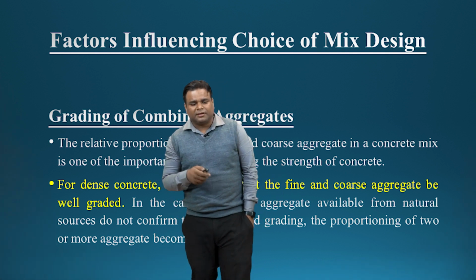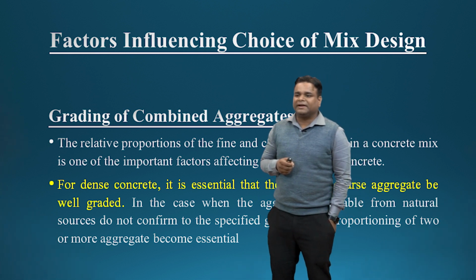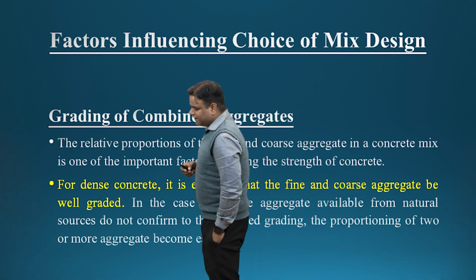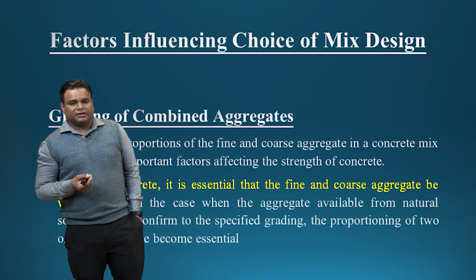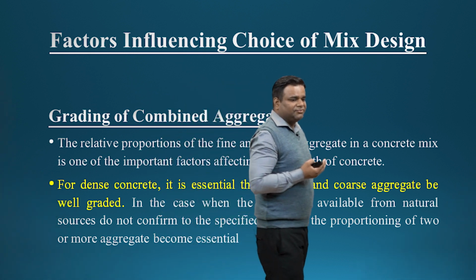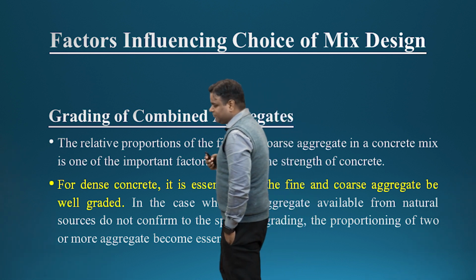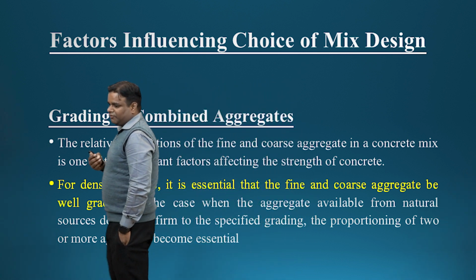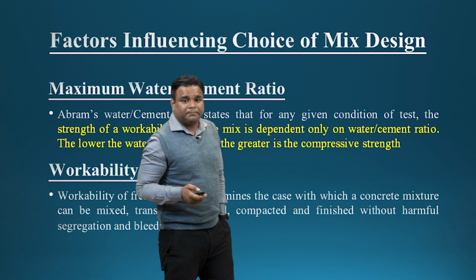Earlier also I have said that we have to use well graded aggregate, because if we are using a single size of aggregate, the packing density is very low. So to get higher packing density and the highest strength, we have to use well graded aggregate.